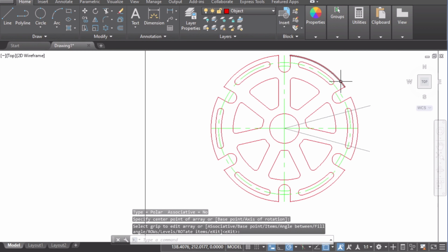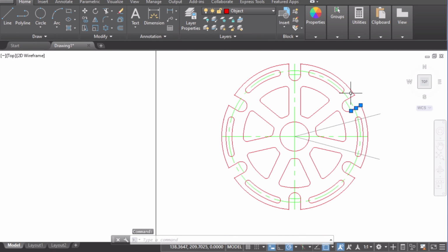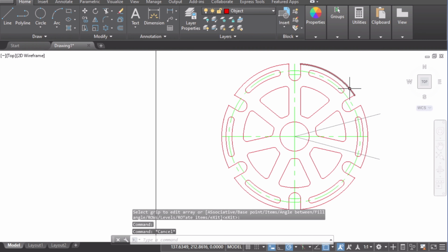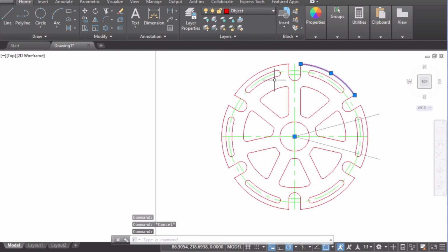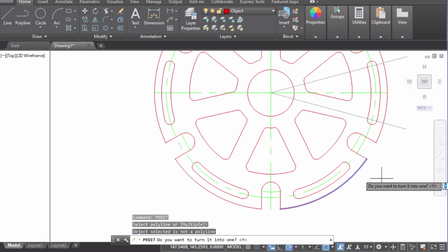And the last thing, I'm going to convert the boundary, the outer layer of this thing, as a single geometry. As we discussed before, I want to convert the boundary as a single geometry. So I'm going to use this command for Polyline, pedit, enter. Then I can choose the border.